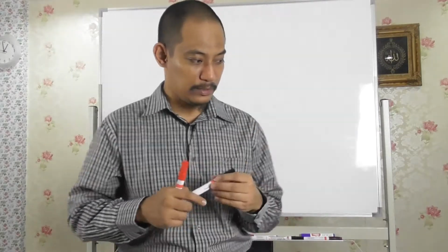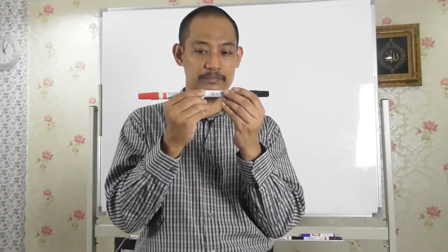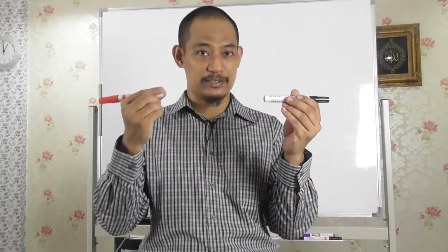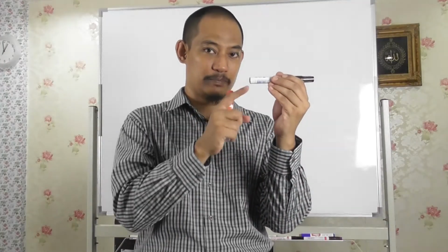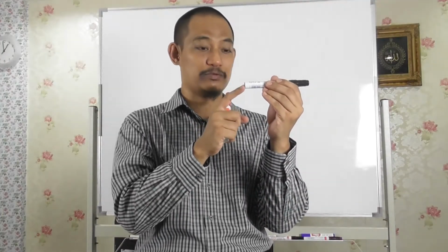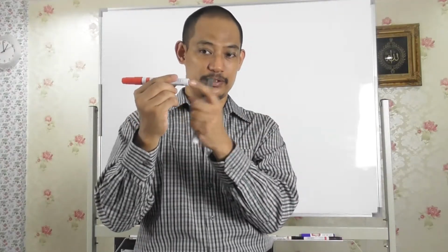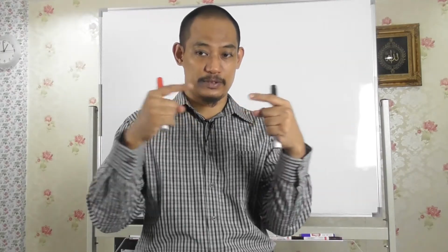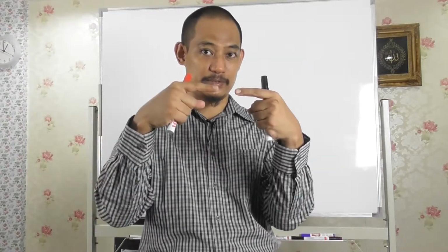And in the following slide, you can see the sign convention for these three components. On the left side, hopefully you can refer to the slide. When you split the member, we can focus on either one side or the other side. Obviously, if you focus on this side, you will draw the normal force, shear force and moment here. If you focus on this one, you will draw them here. Obviously they will be the same but opposite. For example, normal here is in this direction, and normal here is in this direction.